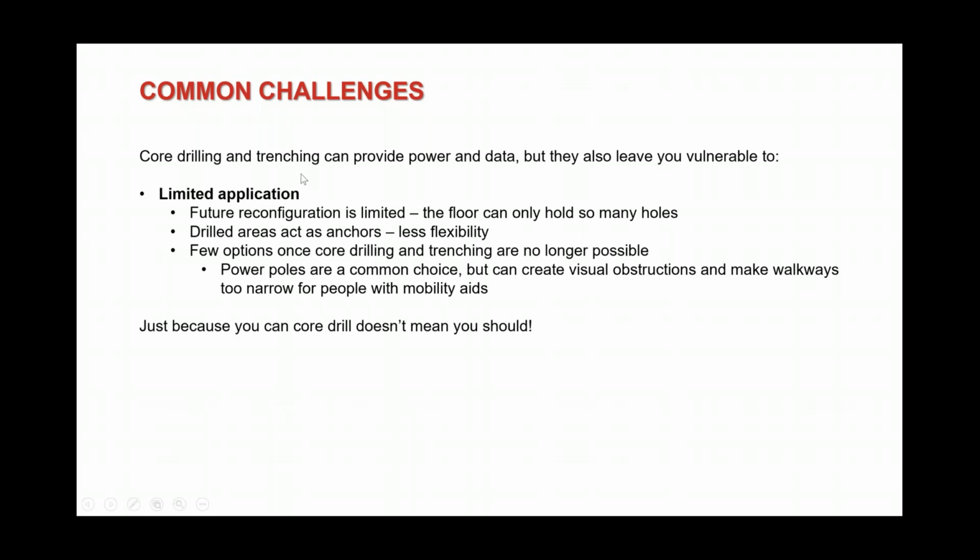The other one is the whole limited application. Depending on what the x-ray shows, the floor can only hold so many holes. You can't put it wherever you want it. Wherever you put an X on a blueprint, you cannot put that. If a president, CEO says, I want this power and data right here, the floor has some sort of cabling in it, some sort of steel in it, it cannot be done.